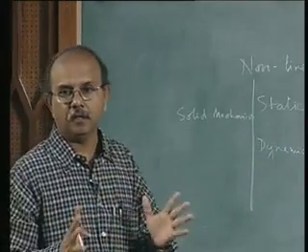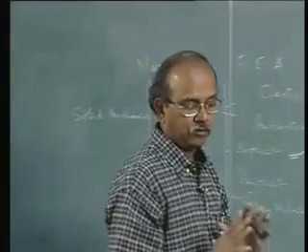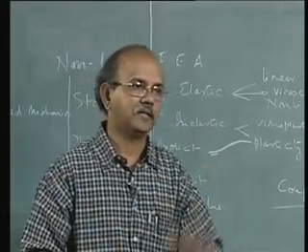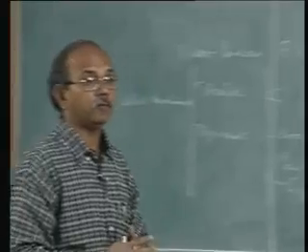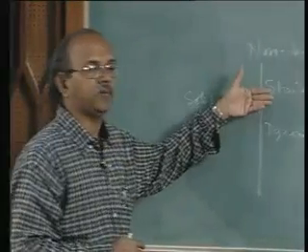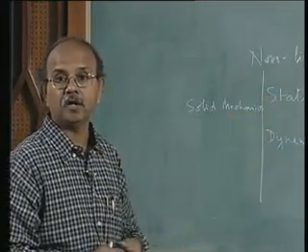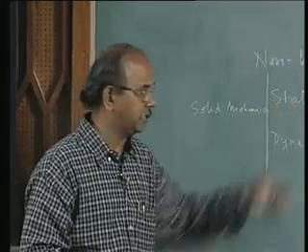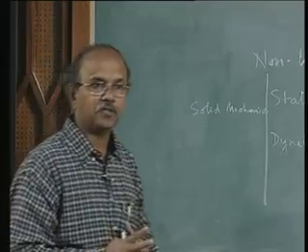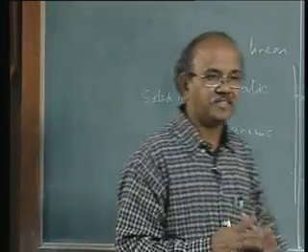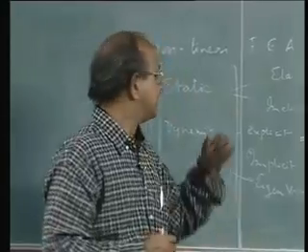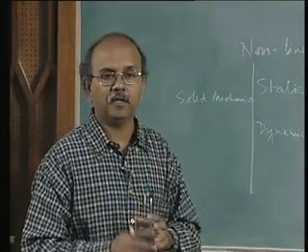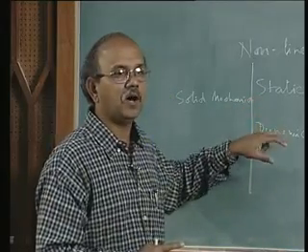Of course, for certain class of problems you can definitely say that they are dynamic or they are static. But certain class of problems, though it may appear to be a static problem, so for example many of the metal forming problems are today done or carried out using dynamic analysis, dynamic explicit analysis, basically because you also have to consider certain problems that may arise during static analysis. So you have to know theory of nonlinear finite element quite thoroughly in order to make that judgment how you are going to do that.